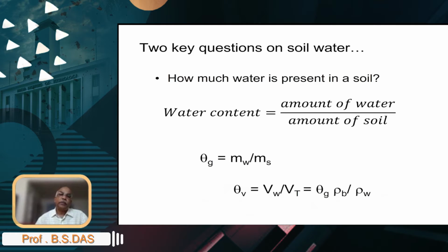So this gravimetric water content is defined in terms of the mass of the dry soil, and not in terms of the moist soil weight, because if you take moist soil weight in the denominator, then depending on how much water is present, the denominator would also change while the mass of water itself is changing. So an intrinsic quantity for the soil wetness will not be possible. And so it's always mass of water divided by mass of the oven dry soil, which does not contain any